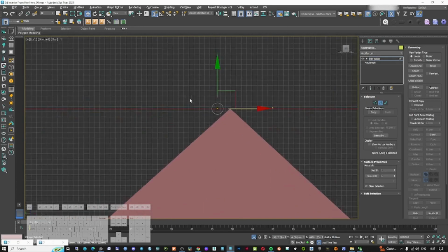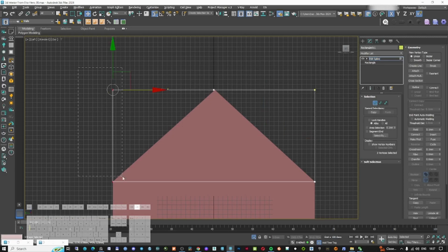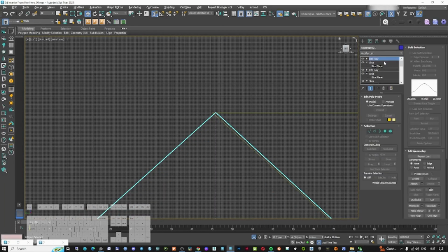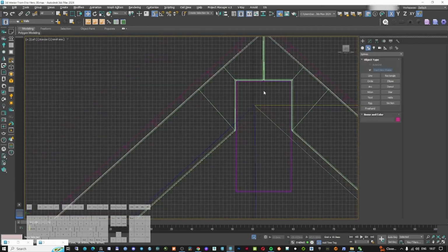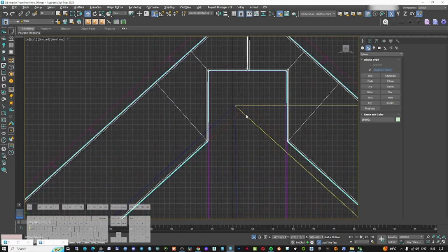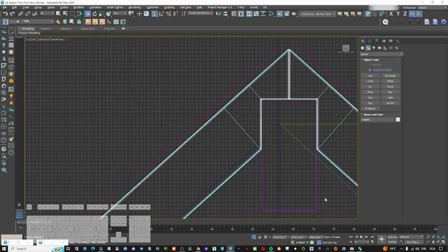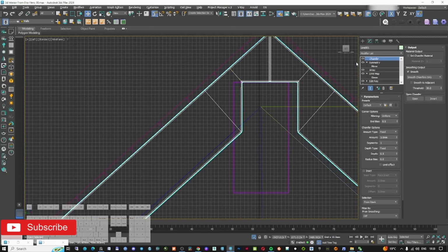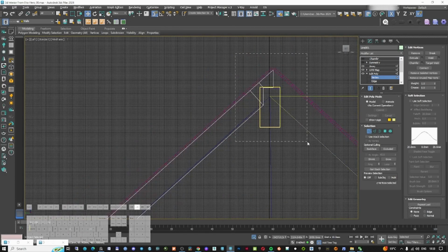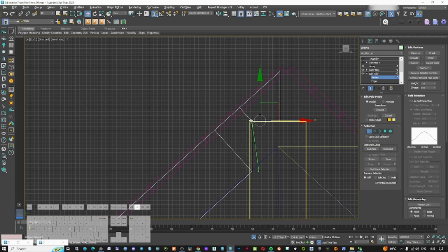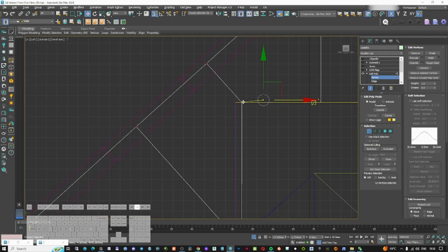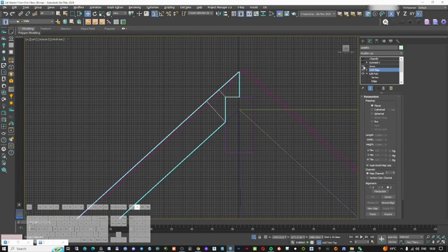So this was not correct actually, but because I made all of this with modifiers, I can change it very fast. So yeah, these kind of things are quite important, to have modifiers for every small thing that you are making, because in the moment that something like this can happen, and most of the time it's happening, you can fix it very fast.